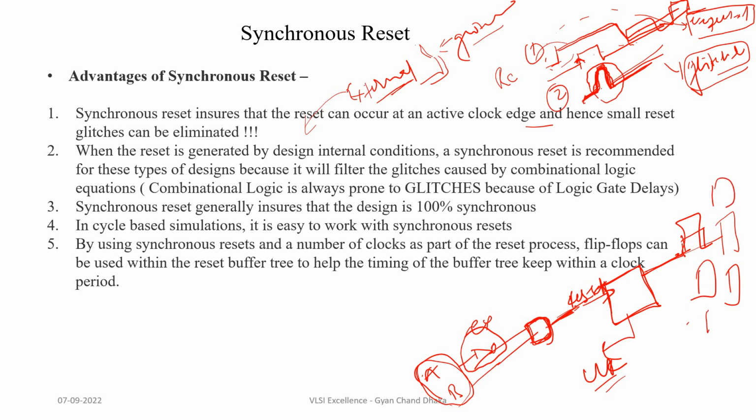So using synchronous reset is advantageous for reset signals which are generated internally and which can have glitches introduced due to combinational logic. This is the second advantage of synchronous reset. Also, synchronous reset generally makes sure that our design is 100% synchronous, and if our design is 100% synchronous, then there are very few chances of metastability.